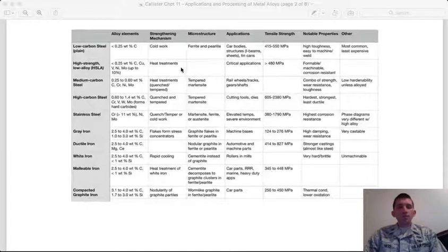These alloying elements slow down the formation of the microstructure, and so you have 50, 100 or so seconds to cool down the material and get around the nose of the time temperature transformation diagram. So you can get to those other microstructures, bainite and martensite, much more easily.